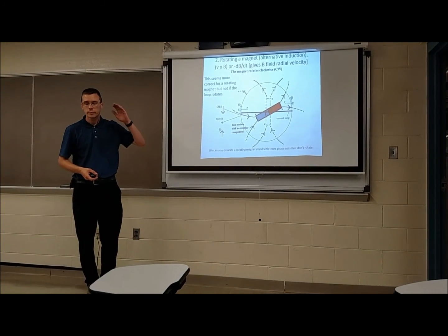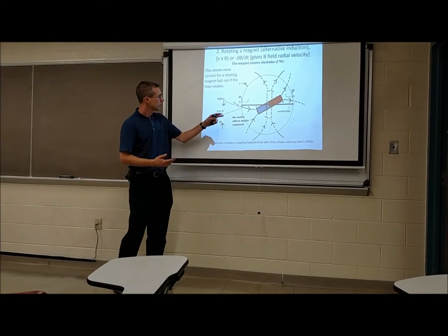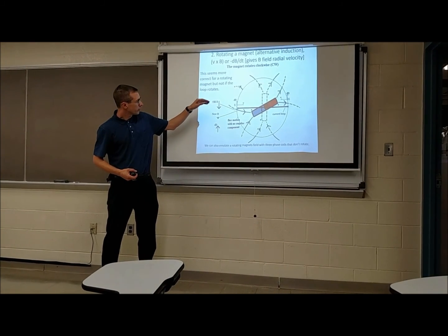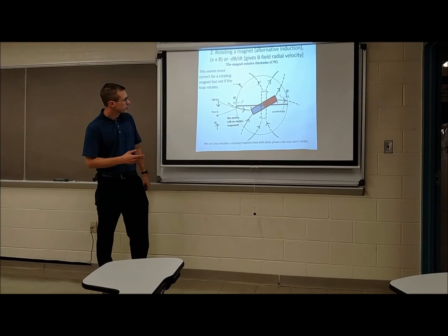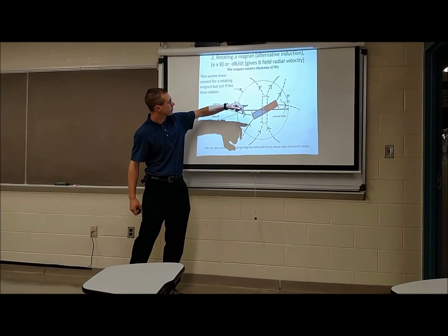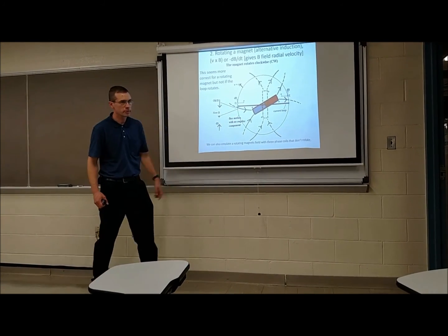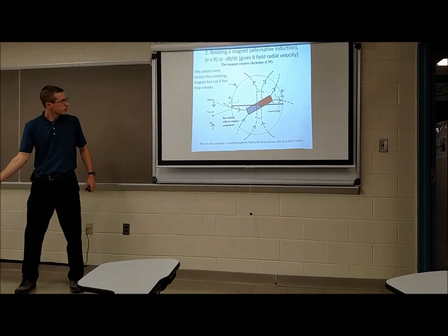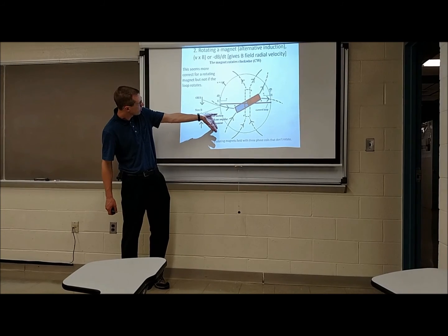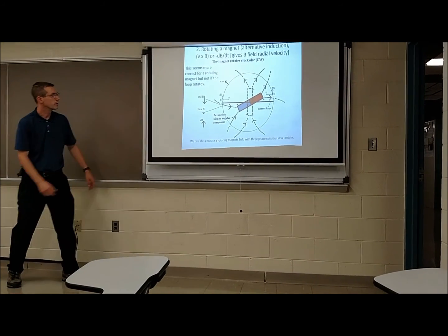And you get the same induction if you imagine the magnetic field rotating as well, I believe. So you have the magnetic field pointing in, but then your relative velocity would be, I believe, pointing for the wire. Which way is this magnet rotating? It's rotating this way. So the magnetic field has velocity up, so your relative velocity would be pointing down if you're a charge in the wire. So you point down, and then you have the B field pointing into the magnet, v cross B, right-hand rule, and again you get the electric field pointing out as well. So it's parallel there.